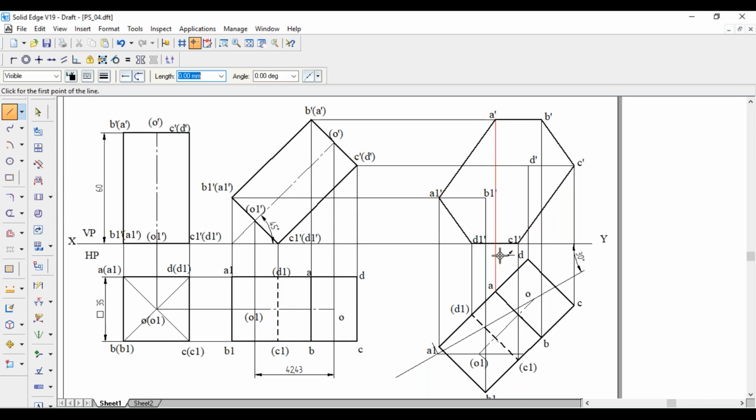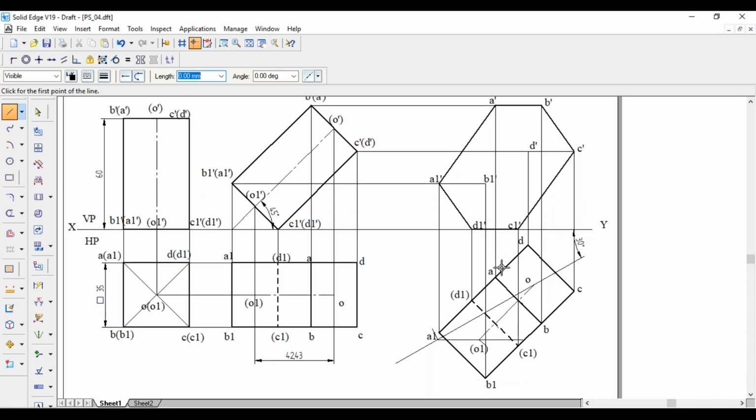Now, in the top view, this is the bottom face. A1, B1, C1, D1 is nothing but the bottom face. The bottom face is nearer to the observer. So here, the bottom face is completely visible in the front view. So join that one. That is A1 dash, B1 dash. That is this line. This is nearer to the observer. Join that one with a continuous dark line. Similarly, B1 dash, C1 dash. That is B1, C1. This one. So that is also nearer. So that is also visible.